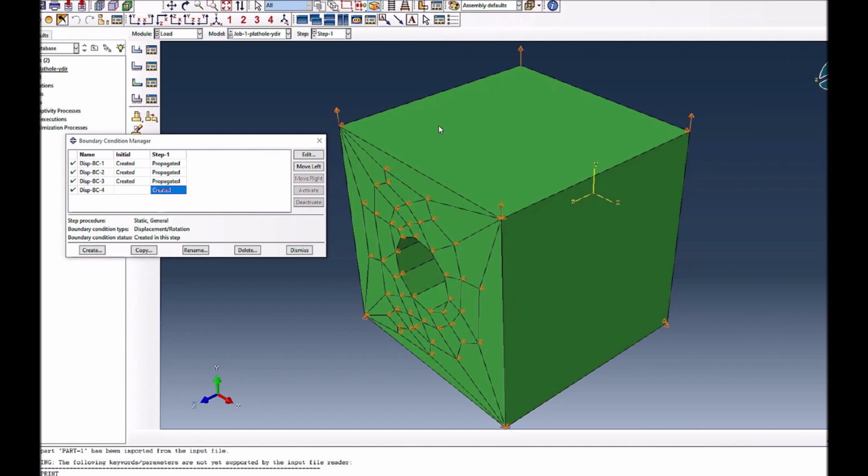So this is one of the ways you select your representative volume element size, or a unit cell simulation model size, if you're modeling a very small part of the whole thing. If you have a big material component and you are only interested in a certain area, you need to select that small representative volume element in such a way that it should at least still have a similar response as the overall thing.